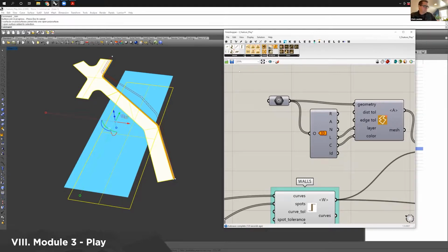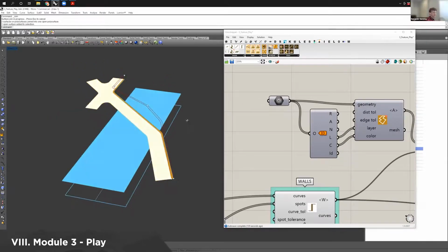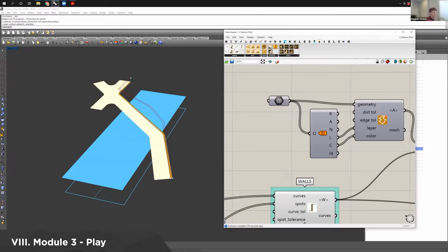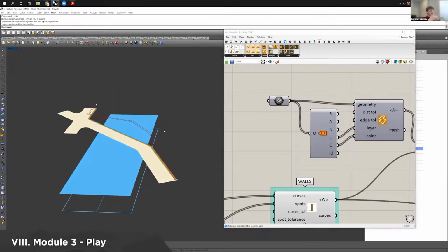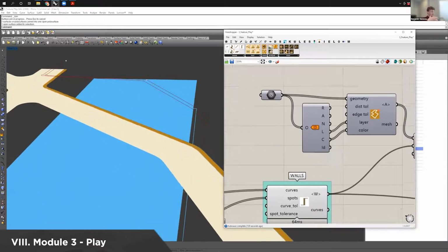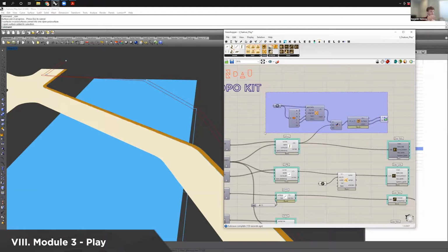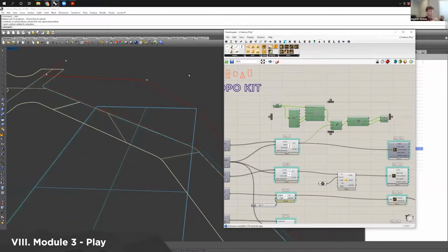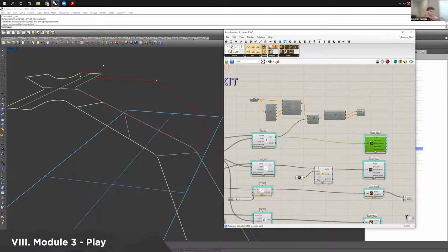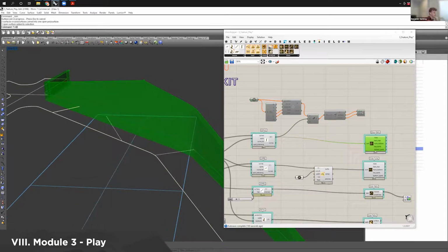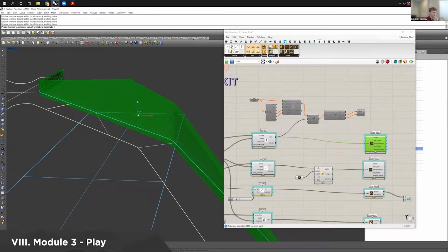All right, now. Another cool thing I wanted to mention about the walls to remember is that the bottom front of your wall can also have a varied height. So you could have varied heights at the back and at the front: bottom, back, top, and front, bottom. So if you're trying to get the wall to meet a specific changing grade at the bottom of the wall, and it's also doing the same at the top, you can add a bunch of points at the bottom of the wall and do the same thing and create those breakpoints for you.